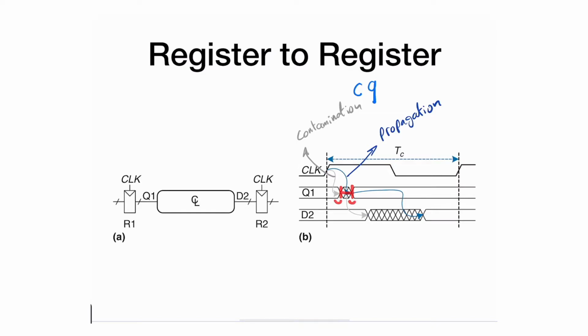And of course, that Q1 is used as an input to the combinational logic here. And this combinational logic, regardless of what it has, also has delays. This logic might make that signal pass through maybe 3 or 4 logic gates, or might end up with more logic gates, like 100 logic gates. So it also has a range of delays. This diagram shows that the output of the combinational logic block might change anywhere between here and here.